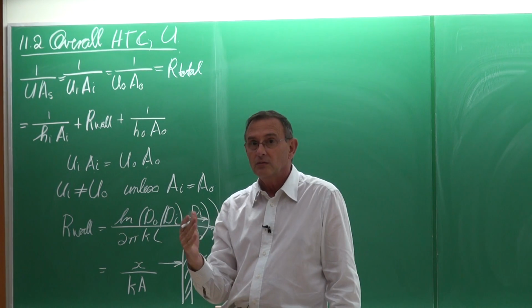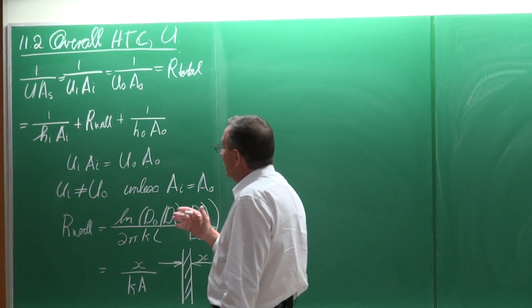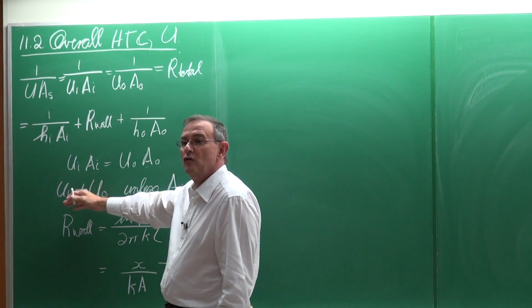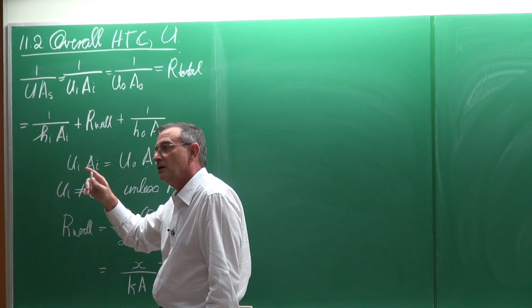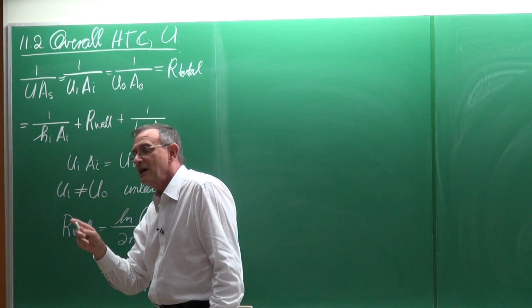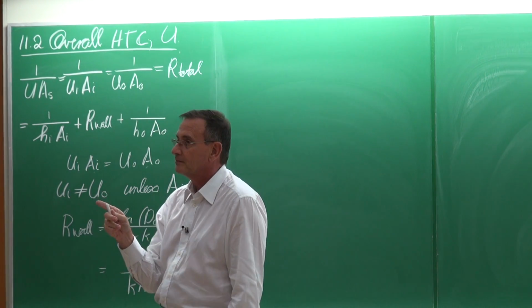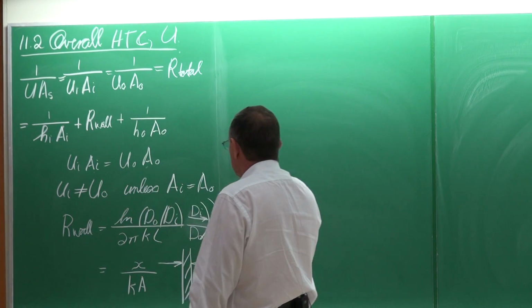But in general, if somebody gives you the overall heat transfer coefficient of a heat exchanger, you should ask, is it based on the inside area or the outside area? Okay, it's very important to always remember that.